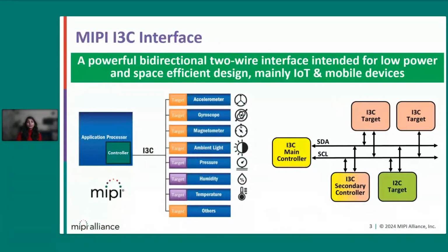Let's first take a brief look at what the MIPI I3C interface is and what the different devices are that can be connected to a two-wire I3C bus. As you all know, I3C is an innovative two-wire interface by the MIPI Alliance, which is the next generation chip-to-chip interconnect. SCL and SDA are the two wires through which data and commands are exchanged between I3C devices. The two-wire I3C interconnect dramatically enhances the speed and flexibility of legacy interfaces, which simplifies the development of innovative designs for products.